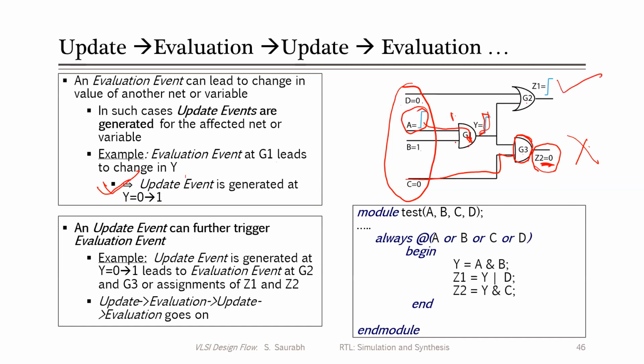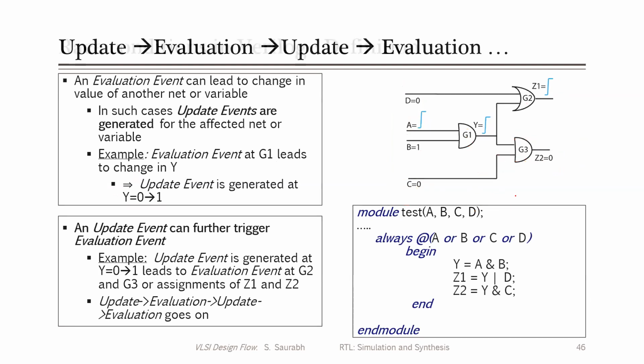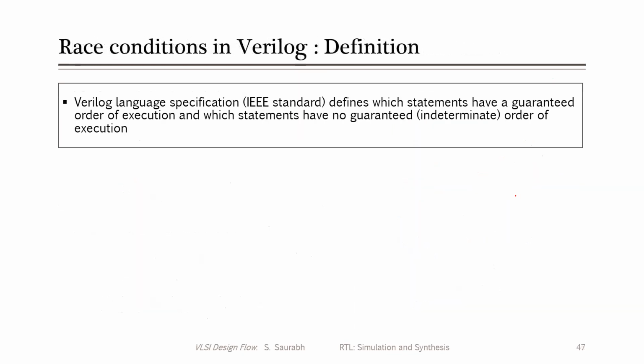And that is what you need to understand. Suppose you wrote a test bench, and now Z2 is not changing. Why is it not changing? The reason is C is held at 0. To understand all these things, you need to understand what simulators do internally. So I will not go more deeply into simulation. I'll just explain a few more things that are important while debugging.